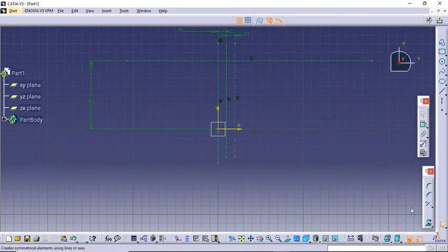Now I can use the mirror image. Let me first click the elements which I want to mirror, click on mirror, and then click on the reference line. So now in total 1, 2, 3, 4, one more line. Click here, mirror it, and click here. This is all.